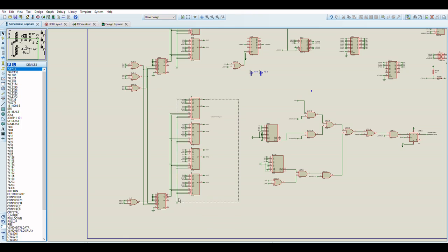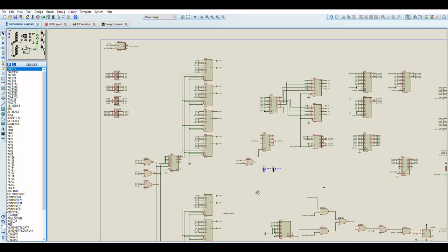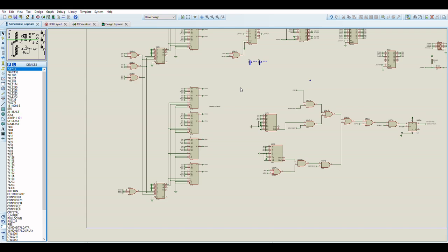So the mode 7 layer was put as a higher priority than the sprites and the background. And this is basically the configuration that can be enabled. So I would enable these here in the simulation, and I would disable these in the simulation. I would then tell the simulation to read the test data output file, the debug signal output file from the emulation as it's running, and it would render the mode 7 layer on top of the sprites and the tiles, and it would show almost the exact same output in the simulation as was in the emulation for the RPG game.